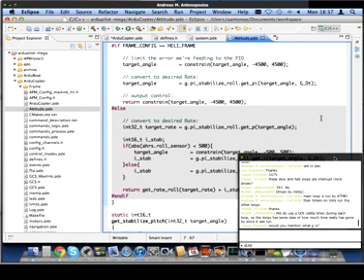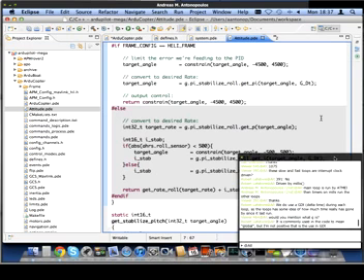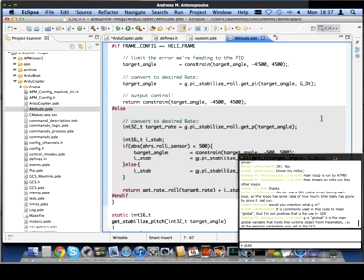And then we pass it into the PID controller. So this g.pi_stabilize_roll is a PID object. And it's already got all of the PID values that you might have set up through the mission planner. All the gains, etc., would be held inside of that pi_stabilize_roll object.